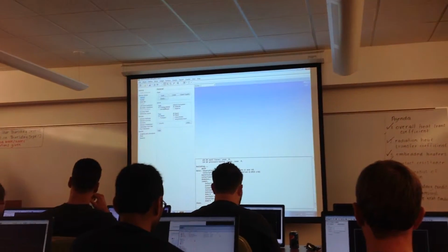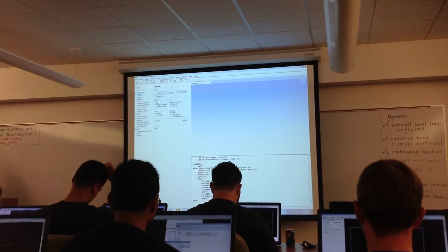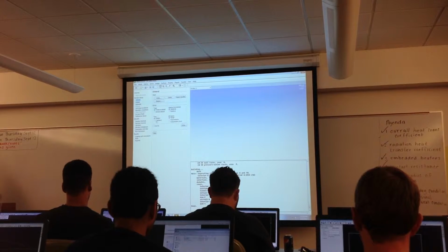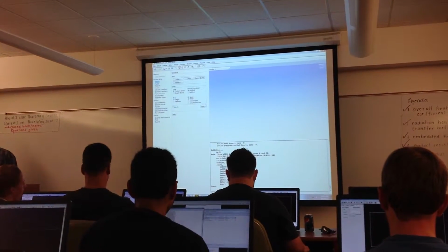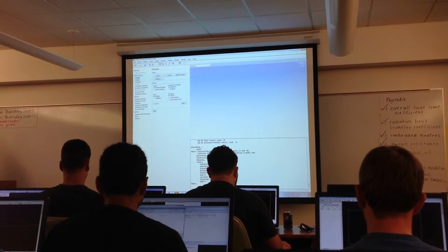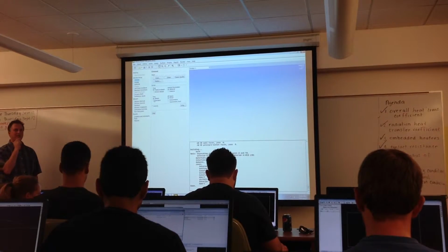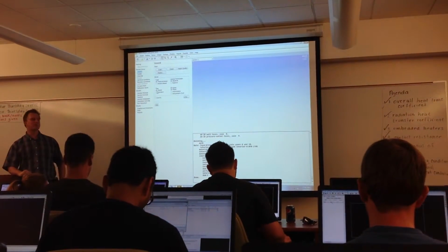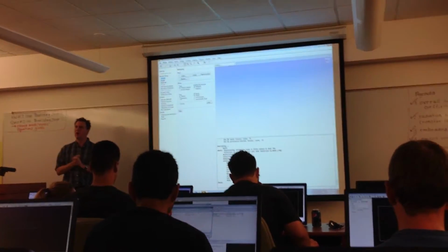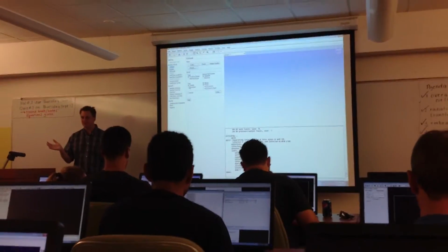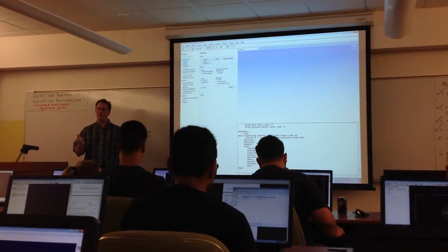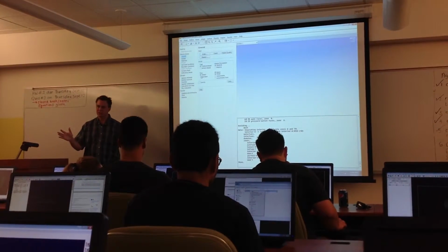Problem, you probably would be using the pressure-based scheme. But this is what we're going to be using. For now, I'm going to have steady flow, which means that we want a steady flow result. We're not interested in the transient behavior modeling. We're not interested in creating the animation of what happens in the flow behind the airfoil. We want the final solution.